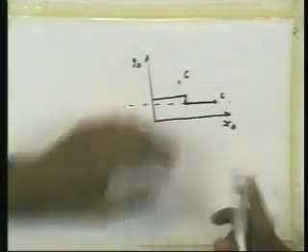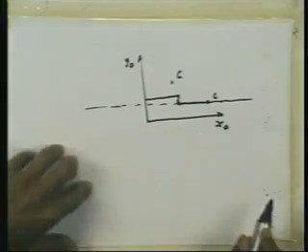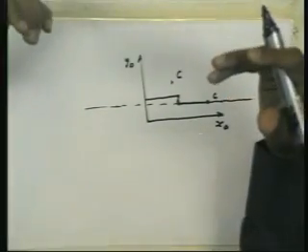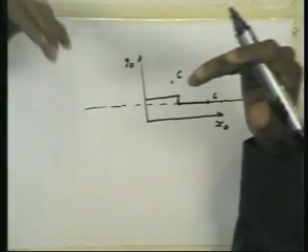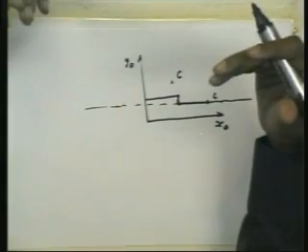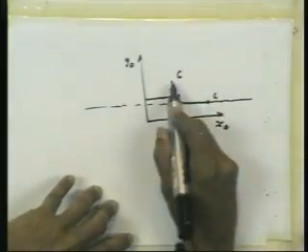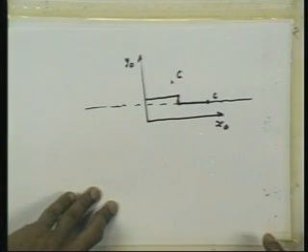Rotate it to bring this particular line, which could stretch from minus infinity to infinity, because in this particular calculation you do not know the restriction whether it is reachable or not with regard to theta 2 theta 3 motion. Only with regard to theta 1 are we really calculating it. So, this entire plane is brought into alignment with this. How many solutions for theta 1 are there for that? There are two ways you can do it. You can bring this side here or you can bring this side. So, those are the two solutions.